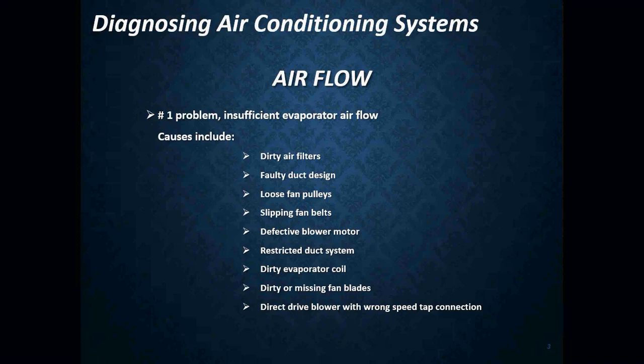Direct drive blowers going in the wrong direction, or maybe the wrong speed tap is actually connected, where instead of it being on high speed, you're going to want it on medium speed or medium low speed or whatever it's got to be for that particular type of air conditioning.